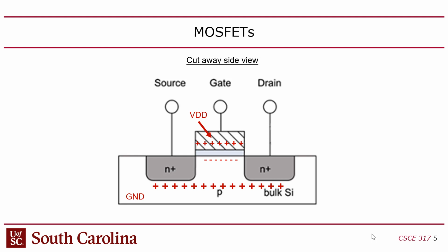And you can reduce the capacitance if you make this smaller. You make the channel smaller, the area of the channel smaller, less capacitance, and thus faster switching. And that's what Moore's law is all about. But now, as I explained with that unit cell, if we're at 7 nanometers, the atoms are only half a nanometer apart. You can't really get that much smaller.